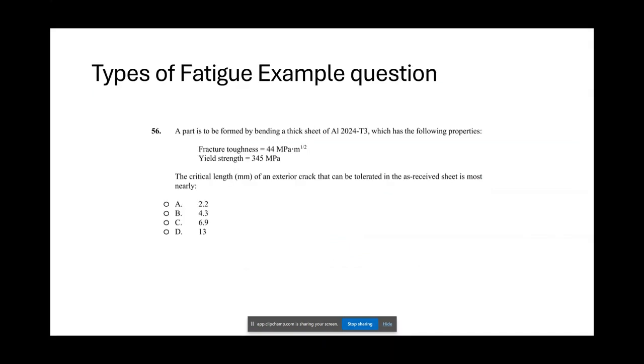Rearranging that fracture toughness equation mentioned before, we're going to be able to develop it to be a equals the fracture toughness over the Y, which in this case is the 1.1 from the handbook, and then the sigma Y as given right here. That would be squared since we're rearranging the equation, and then we'd have 1 over pi. All in all, we go ahead and solve.